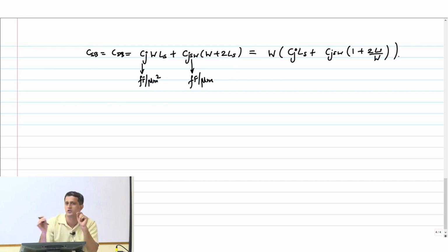You can optimize your circuit to get minimum delay, because if I increase W, resistance is coming down but capacitance is going up. Of course, if I multiply these two components, it seems to cancel out, which is true. What is known as parasitic delay of a transistor is to a first order independent of W. Parasitic delay is due to its own capacitances.